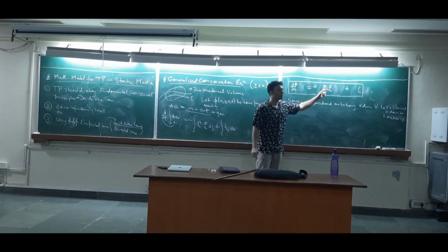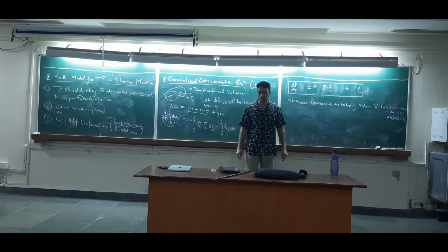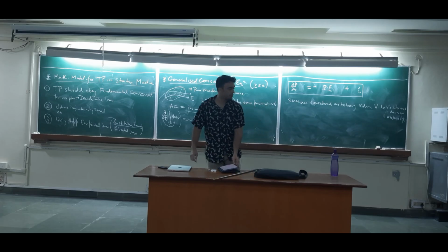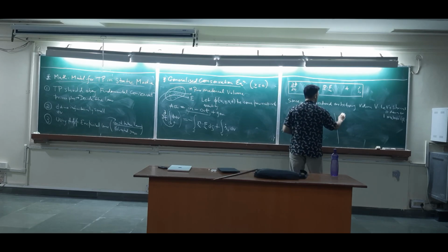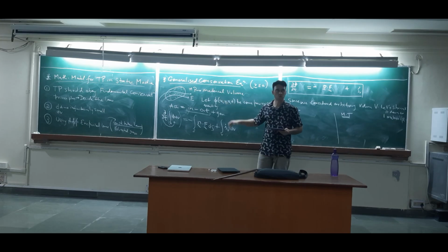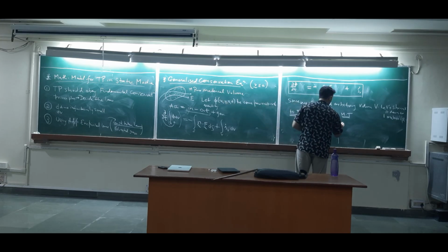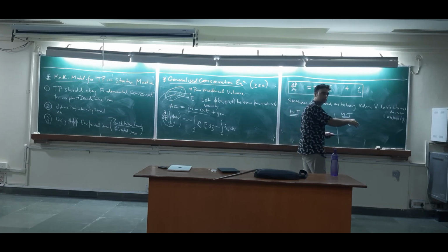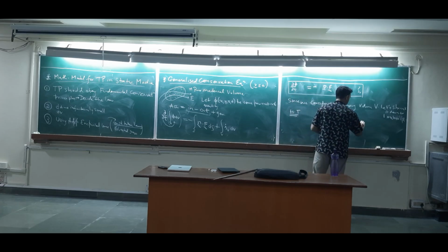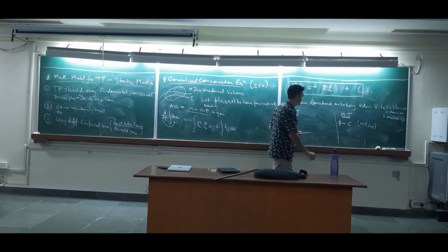Now we have to supply F, this flux. Again, we have two candidates here which we are studying: heat transfer and mass transfer. So now I'll make things more explicit. What phi could be? In mass transfer it's easy, so first let me write that. Let phi be some per unit volume quantity. So in mass transfer it will be concentration. Is it per unit volume? Right? Units are mole per meter cube, SI units. What will be the flux?